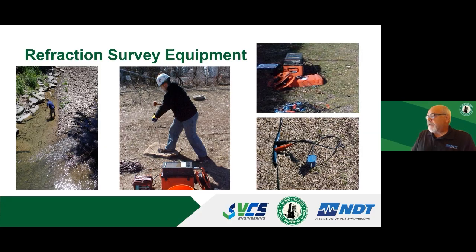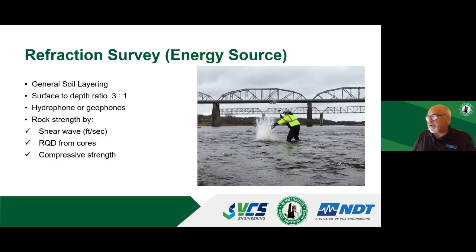So again, this is very effective, very portable, and good to collect general soil profile information, not detailed, but general prior to a subsurface investigation. You might be able to cut down the number of borings, or you might be able to locate them in a particular area.